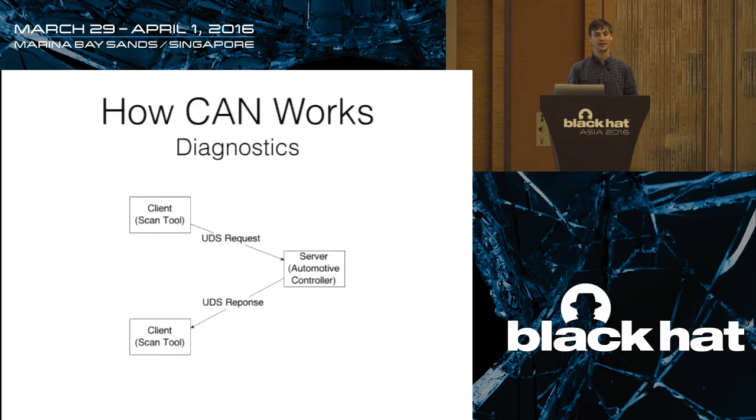And they wanted to be able to get data on vehicles for the purpose of being able to do smog tests, because in order to look at the emissions of a vehicle, know what the vehicle's running, and actually be able to tell what the emissions were, you need certain information on airflow, fuel flow, things like that. So they came up with this OBD, which is really a read-only protocol. The only thing you can really write with OBD is you can clear fault codes, but you can read out what are called PIDs or parameter IDs for all sorts of stuff.